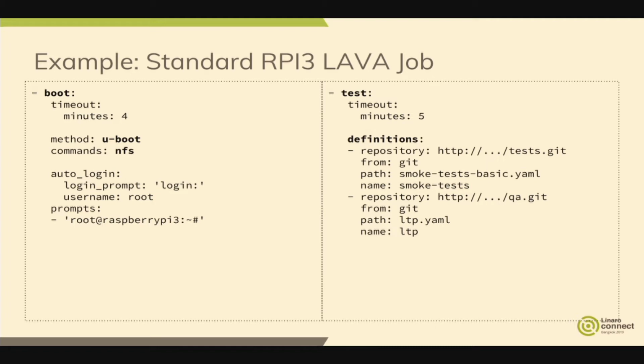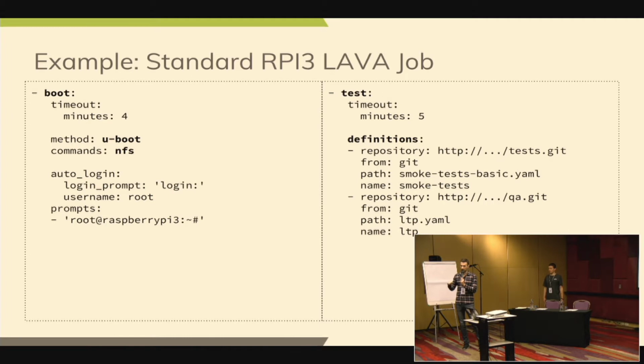Then come the boot actions. Here we select an NFS boot action. That means that Lava will automatically interrupt the bootloader in order to run the kernel with the right NFS parameters in order to boot and mount the rootfs over the network.